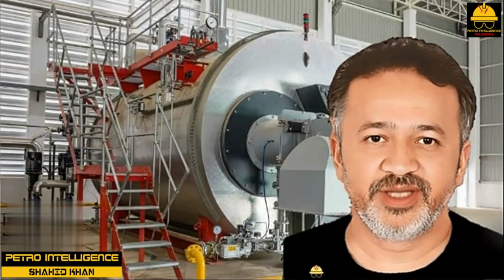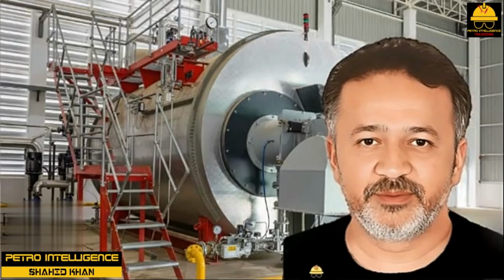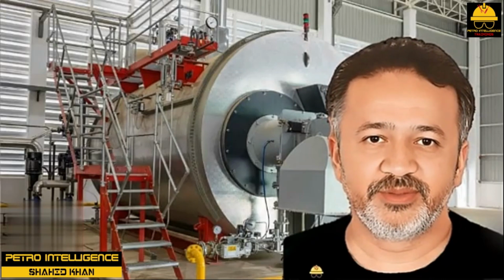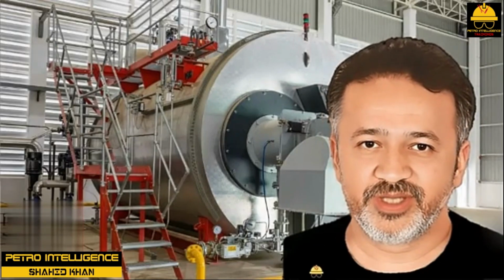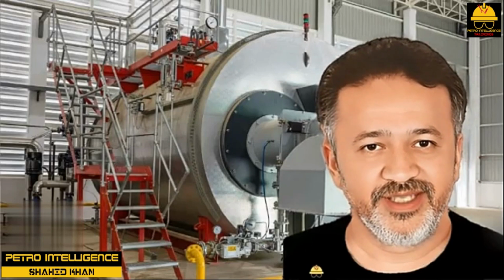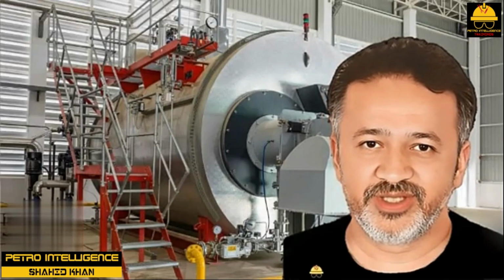The original steam condensers were barometric condensers, which were used to increase the efficiency of the steam-driven reciprocating beam engines by a factor of 10. Exhaust steam is mixed directly with cold water. As this creates a vacuum, the barometric condenser must be elevated about 30 feet above grade. The mixed condensate and cooling water drains through a pipe called a barometric leg, hence the name barometric condenser.